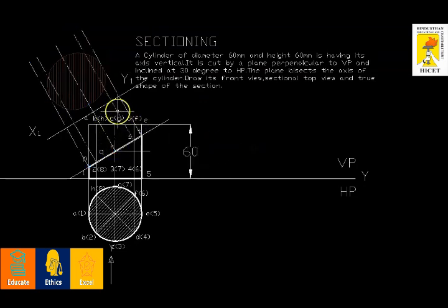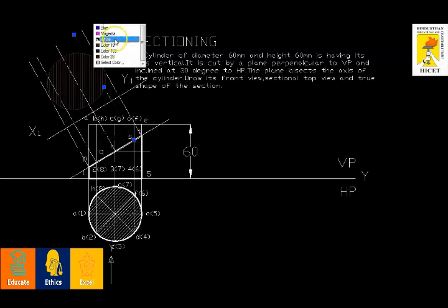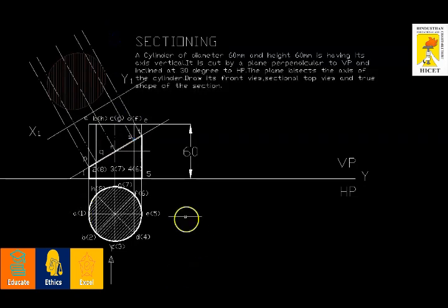After projecting the cutting points, I'm going to take a compass. I'm going to measure the distance from xy. See, we have projected this point now. So from xy, I'm going to measure this, and I'm going to transfer it here, from x1 y1. Similarly, I'm going to do it for all the points. Finally, I'll get points here, here, here, here, here, and here.